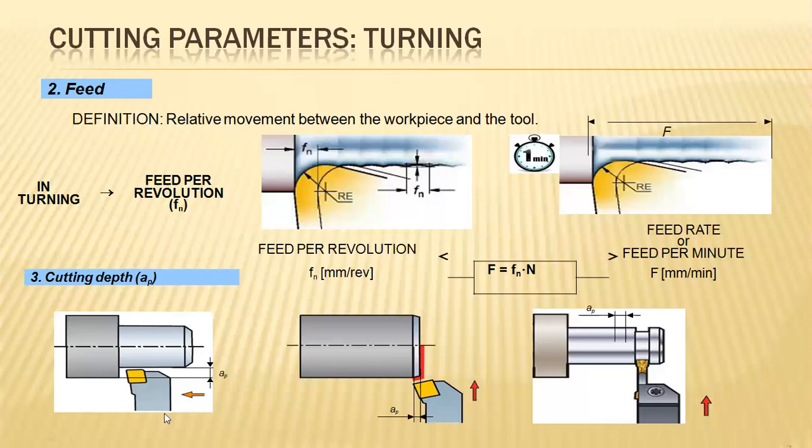In the pictorial representation, we had a detailed discussion that this is the AP, and this is the original diameter, and this is the length and existing diameter. For example, it is 40 mm and we are having 30 mm, and hence 10 mm of the material is removed by considering a feed rate per revolution.